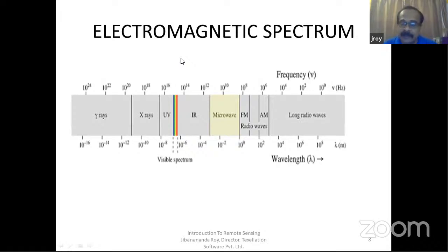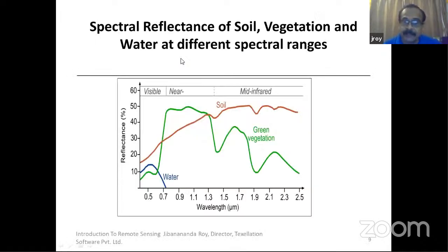the visible and the infrared. The infrared is sometimes subdivided, which is known as hyperspectral imaging, because we are taking images in different spectral bands. So 30 or 40 years back, it used to be multispectral, that means you had 3-4 different spectral bands. But now there are so many narrow bands in which we take images, so it is now called hyperspectral.